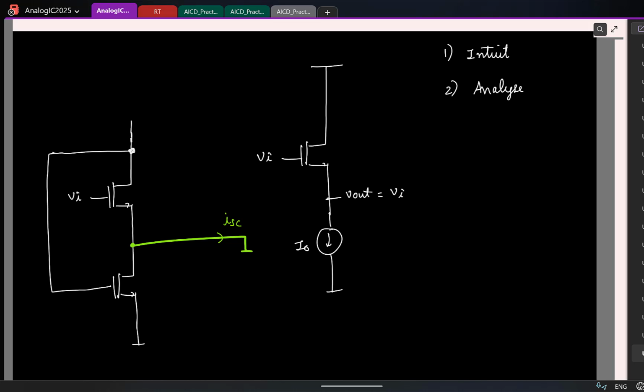Okay, and remember, for small signals, a transistor acts like a what? Voltage controlled current source. So what is the current that will be pumped in by the transistor? gm times Vi. So let me mark it here. This is gm times Vi, and you also have the R naught of the transistor. Okay, I have not labeled the transistors. Let's all keep it gm, R naught. It's okay.